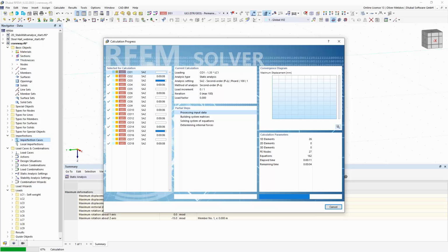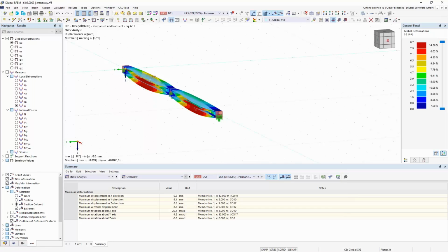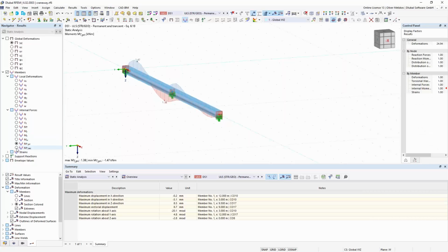So I could use these internal forces in a cross-section design check, and that will replace my stability design check for lateral torsional buckling. So that is possible according to Eurocode 3, and then I could use those internal forces. So all the internal forces I get now in this design situation number 1 can then be used also, for example, in stress-strain analysis add-on or also in a steel design add-on.